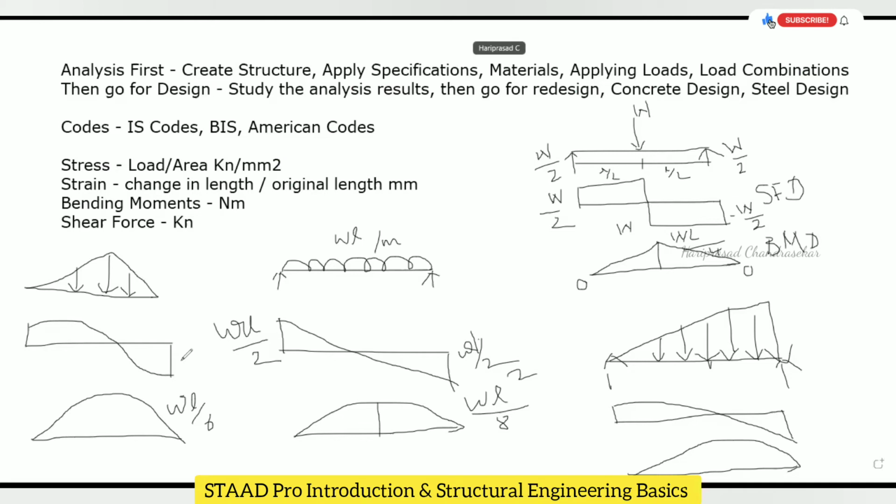And is it acceptable in DM? You mean here, Dubai Municipality? Yes. Dubai Municipality mostly accepts ETABS. ETABS stands for Extended Three-dimensional Analysis of Building Systems. This is mainly for buildings, not for anything else. If you want to create bridges and everything, then you need to go with STAAD Pro, because for analysis of bridges, this kind of thing, you can go for STAAD Pro. In ETABS, they have that disadvantage.